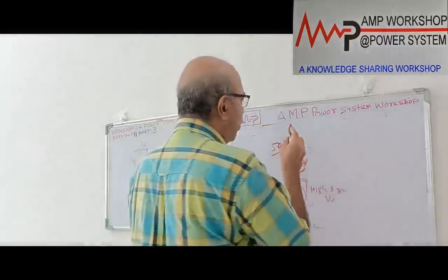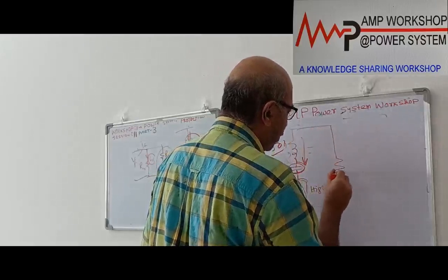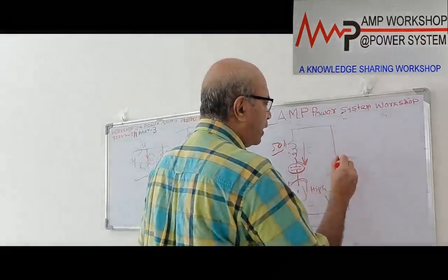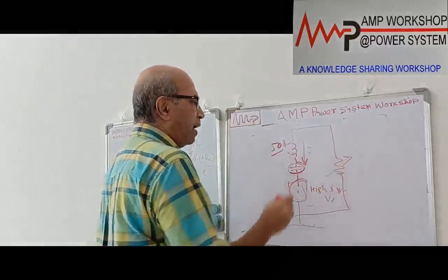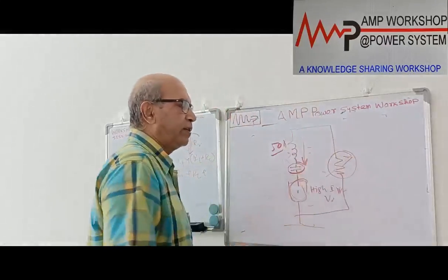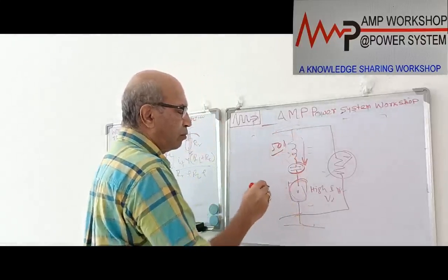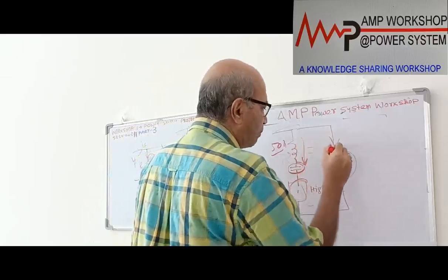To avoid the overvoltage across this relay, we put on a metrosil non-linear resistance. You know, this is a non-linear resistance. What is happening over here is, as the voltage increases, the resistance value decreases. So when a high voltage comes across the relay terminal, instead of damaging the relay, the high voltage passes through this metrosil.